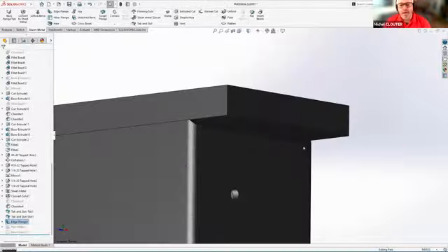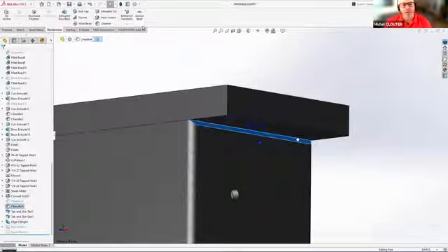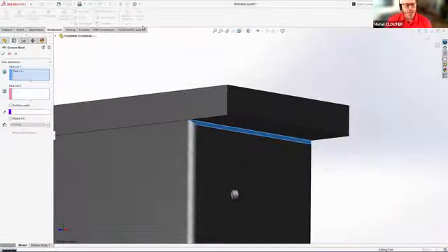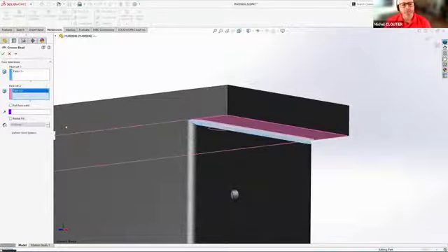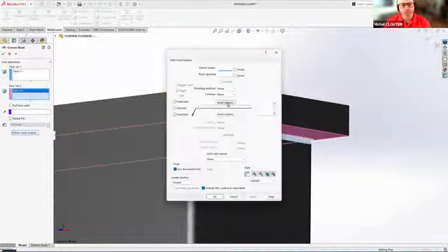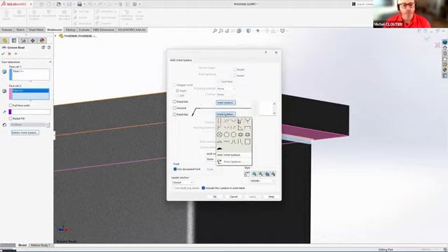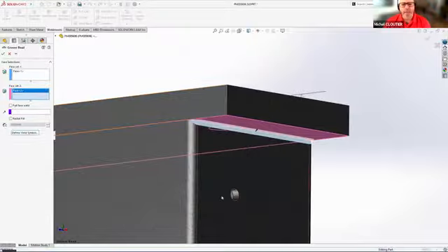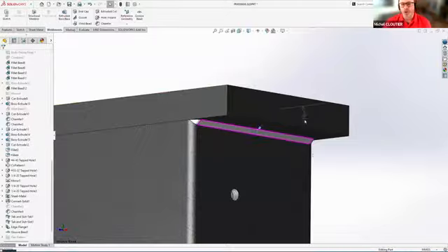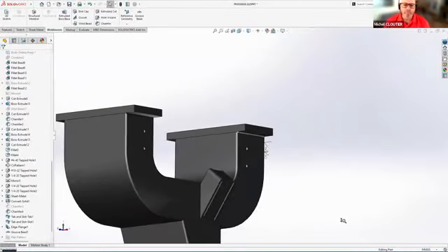And the last thing I want to talk about is groove beads. So you saw an example earlier. Here's another one that's typically more used in weldments and sheet metal cases. So we have that groove bead with full support for our weld symbol. So I can define the groove bead in my assembly and annotate that directly in the 3D model. So that annotation can go on a drawing later on if I need to.